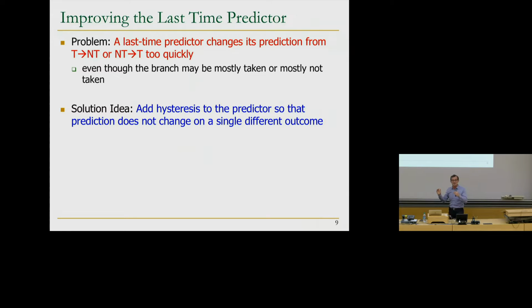So usually these systems are designed such that you have a buffer. The heating or cooling system doesn't kick in until you actually go below a threshold. You don't change your mind so quickly at the threshold value. So maybe you say, only after the temperature reaches 21.2 degrees Celsius am I going to start heating the room. But if it's between 21.2 and 22, I'm not going to start heating the room because I may go into this oscillation mode. So you basically look for more evidence that the temperature is actually decreasing. Make sense?